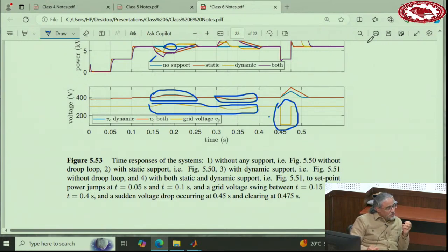You are choosing very small R1, you are choosing gamma equals 0, you are choosing very small C, which means you don't care about inertia, and you want to have very tight voltage across the capacitor. This is a very extreme case. In this case, as I explained here, you need to go through that full state feedback and use K3. But other than that, my experience is K3, don't use it. It makes complications in implementation.